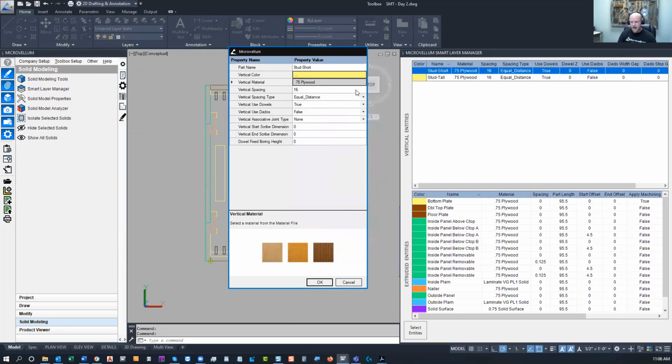You can give spacing options: what distance do you need, and also how are you going to space those? They're going to be fixed based on the distance that you have specified here, or are you just going to divide the whole length by that amount and then equally distance the quantity.